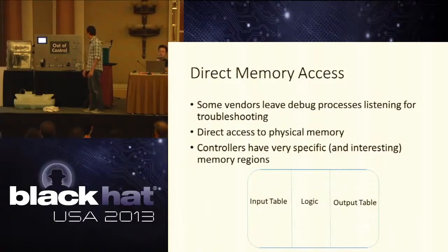Yeah, so some of the common vulnerabilities we've seen in several different devices we've looked at involve direct memory access, where we can use a debug process that is often left on the devices by the manufacturer for troubleshooting or service purposes, and you can manipulate the entire memory space to control anything you want.